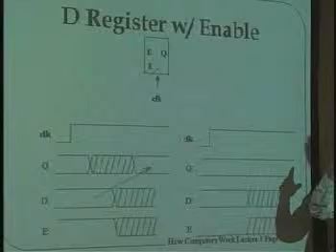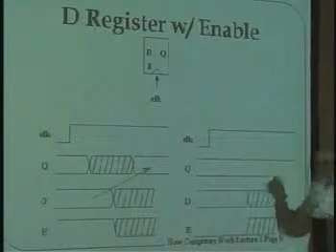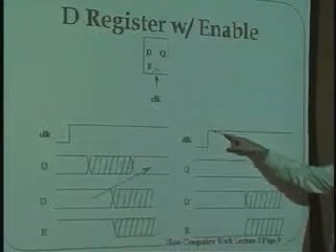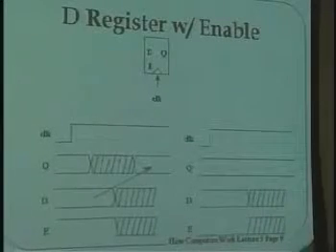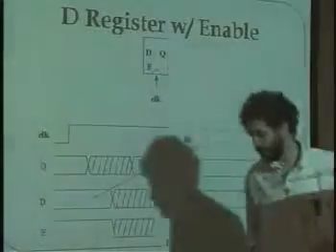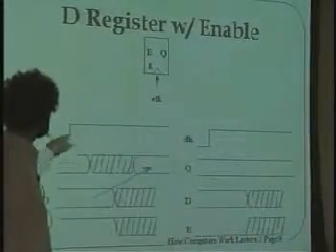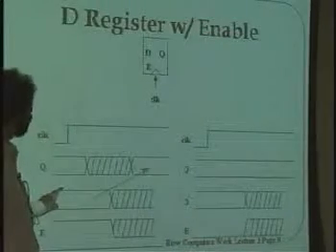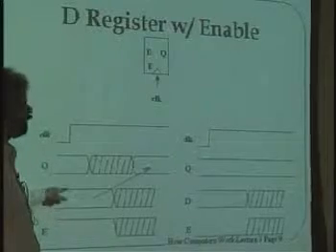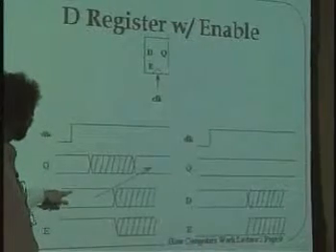And saying that I press the shutter is like saying that I go from a 0 to a 1. Okay? And this is time going by on the x-axis. The idea of how the register works in this timing diagram is that this is the shutter that goes off here. It goes click, right? And here's the data. We don't know if the data is going to be a 0 or a 1, so I express the ambiguity.